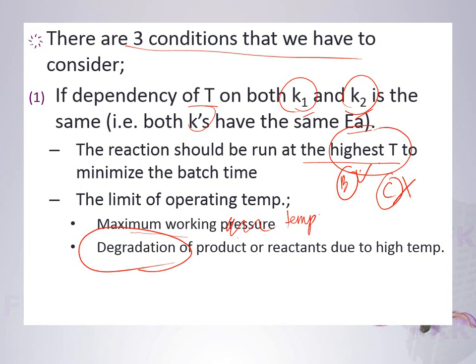No. Number of stages will determine the efficiency. We are talking about the reboiler in the distillation column. It is the same as this case. Because you have to run the high temperature in order for the separation to occur, to have a better separation, but you cannot exceed the degradation temperature. So how are you going to bring down the temperature, but the separation still can occur?